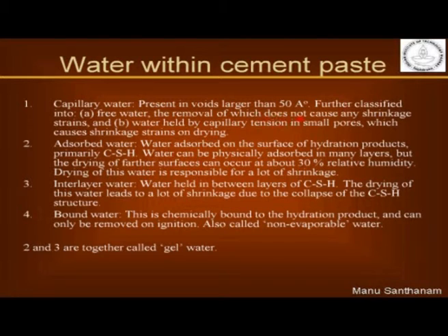So when you remove this free water which is present in large pores, it does not cause much shrinkage in your concrete. But then water which is held by capillary pressure or capillary tension in small pores, if you try to remove that water, it causes a lot of shrinkage. Why is that? Again, you remember your basic physics, when you have very thin capillaries, you have a great rise of water inside the capillaries because the capillary pressure is high. When you have large capillaries, water does not rise inside very much because you have very low capillary pressure. Similarly, if you have a water filled capillary which is very large, if you try to remove water from there, it will not produce much capillary pressure, so your shrinkage strain will be low.